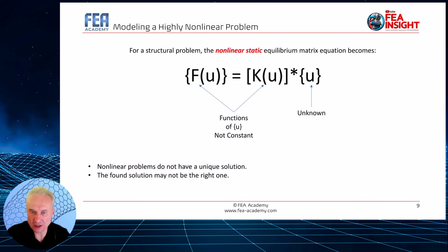So it is not possible to solve for the displacement vector immediately, directly I should say, because the stiffness matrix and the load vector are not known in advance. So the classic decomposition method, the LDL decomposition method that we are using to solve a linear problem, is not applicable to solve the problem directly.